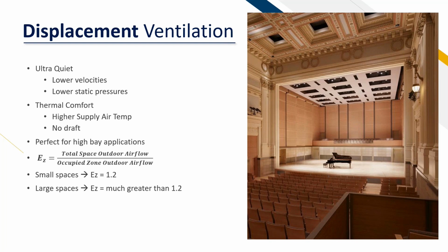Once you get above that, we don't have to go away from displacement. We can utilize Price Predict's team and some different products from Price and come up with a solution. One solution we've done in the past was a space about 120 feet in length. We had displacement sidewall diffusers on each side covering those 35 feet, and then we utilized overhead displacement directed down over the aisles.